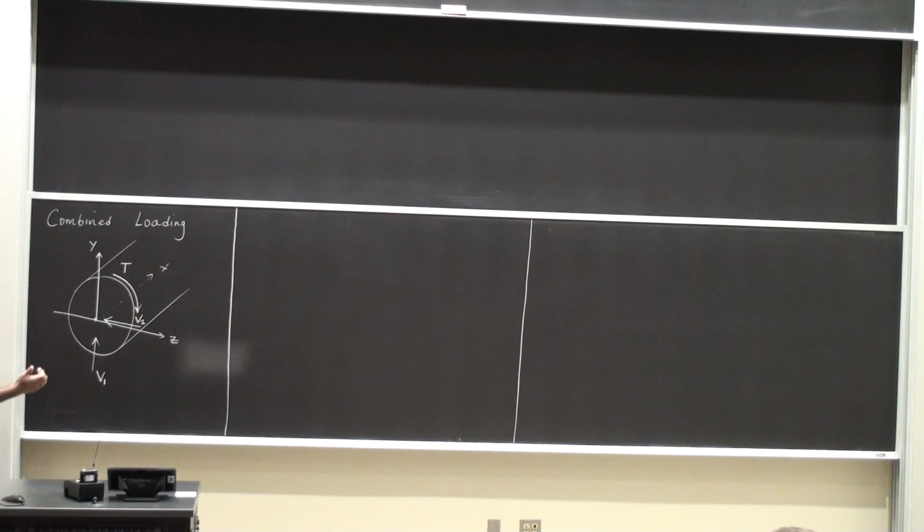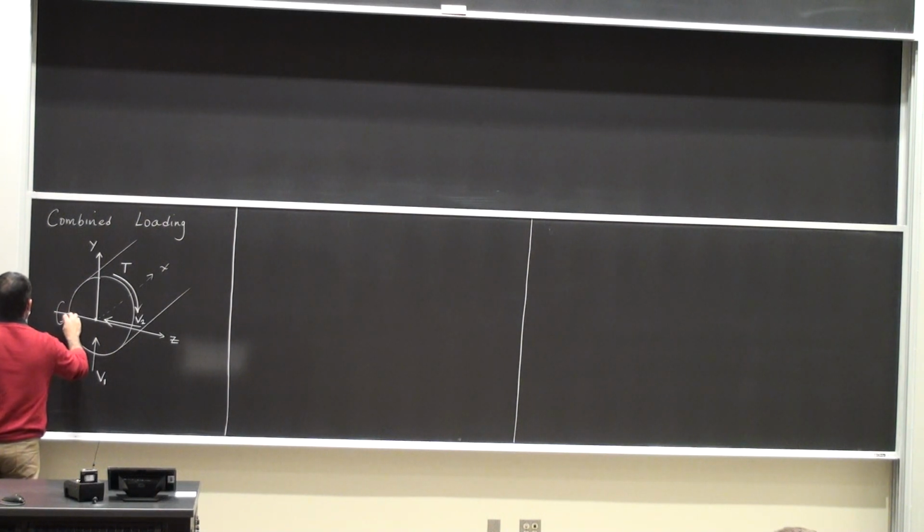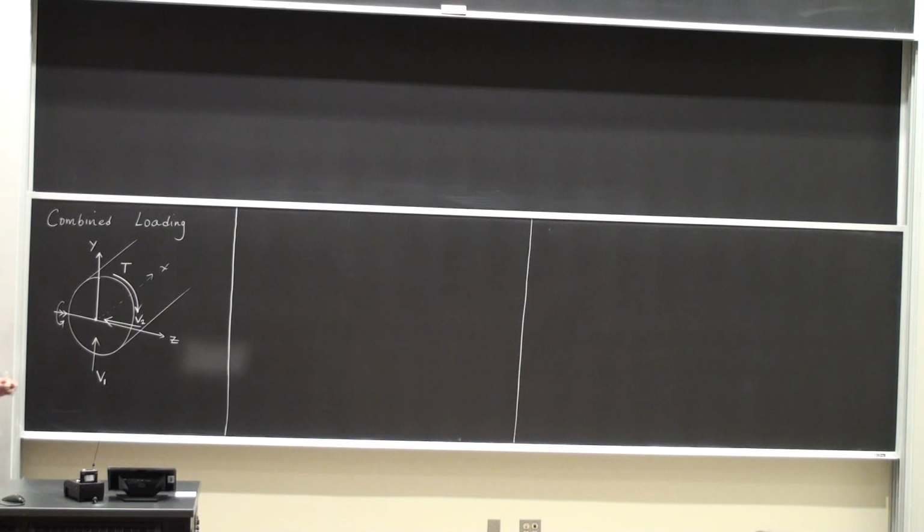One about the z direction. What does this signify? It signifies that this moment is acting, I'm going to call that moment M1. This moment is acting in such a way that if I use the fingers of my right hand and clutch the z-axis, my thumb is pointed along the positive z direction. So that's one bending moment. I'm going to have one more about the y-axis.